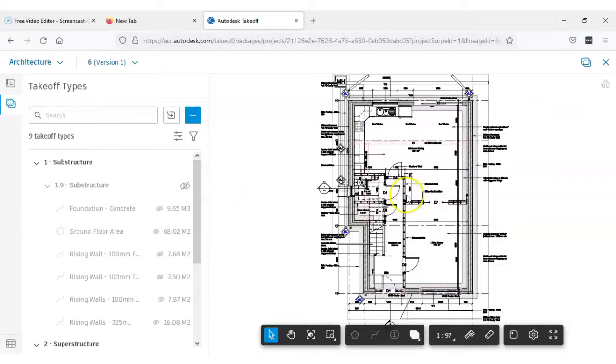External walls are those walls that are the external enclosure of the building, not the internal walls. They're designated as different wall types, or a different elemental category or work breakdown structure in your bill of quantities. Now remember, again, just to reiterate what I've said before, these are just Takeoffs. They are not bill of quantities items. We may use a number of these Takeoff items in a bill of quantities item.